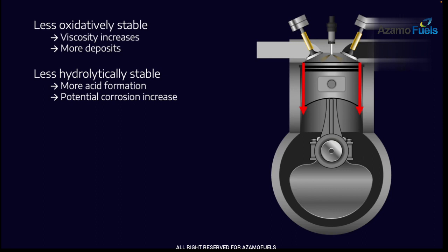right, it breaks down back into an acid, right? So we are creating acids all the time, and then we can run into problems with corrosion, and particularly in the crankcase, we'd be concerned about the crankcase bearings. So that hydrolytic stability can really be a problem in engines because remember, water is also a byproduct of combustion, right? It's unavoidable that water will get into the crankcase. So the combination of water plus a bio-derived ester means that you're going to be producing acids.